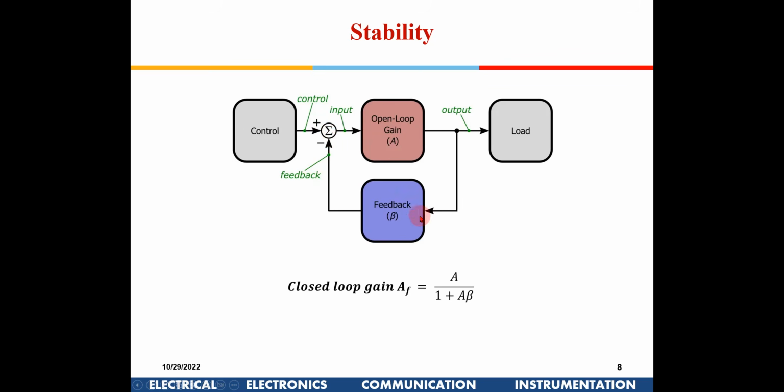Okay, from here to here, the gain is more than 1. What happens? Then that will get further amplified here when you add this. So this will continue oscillation. So there are 2 conditions for oscillations to happen. First is, as the signal moves from here to here and comes back here, it should make a 180 degree phase shift. And then also the gain should be more than 1.